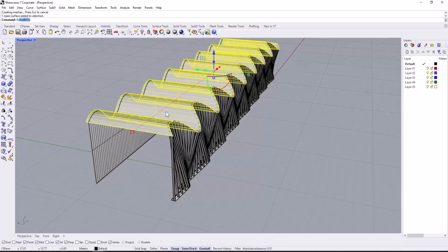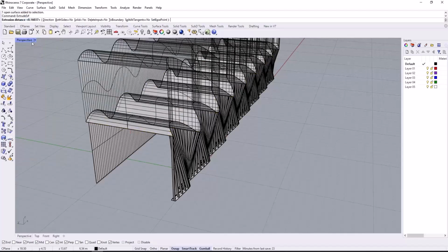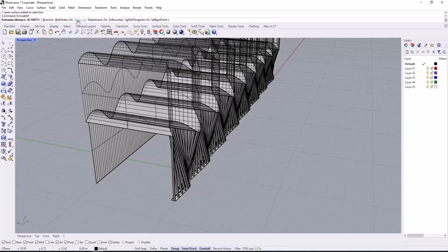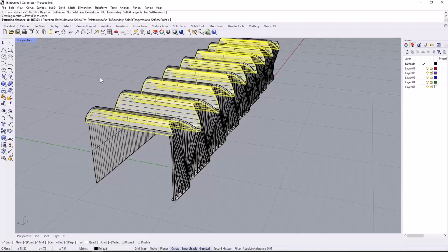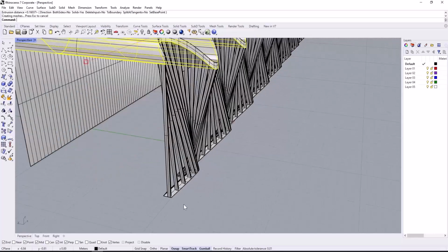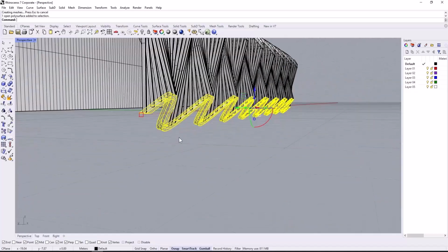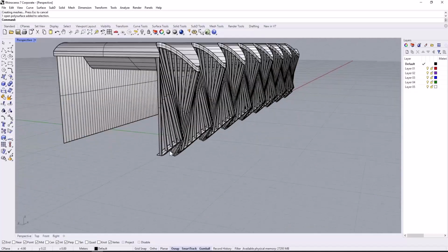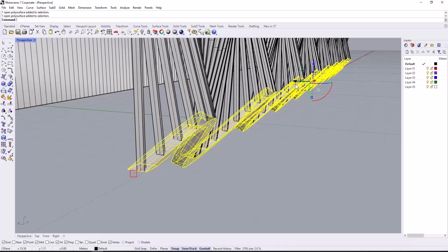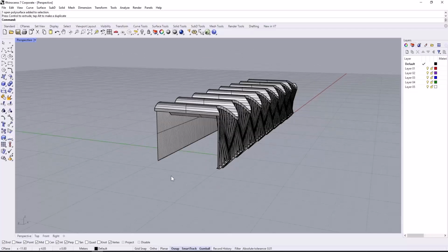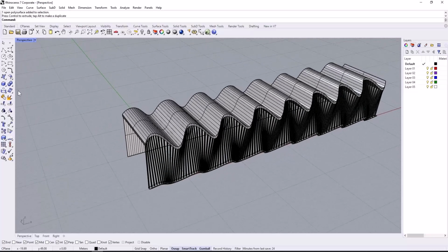Now I address the roof, which currently lacks thickness. I select it and use extrude surface again to give it a volume. I ensure Solid is Yes again so that it forms a closed object. All right. Finally, I check the bottom section to ensure it aligns correctly. If necessary, I make a minor adjustment to bring it slightly forward for a better fit. To ensure the model is centered, I make a slight adjustment like this by moving the structure forward.